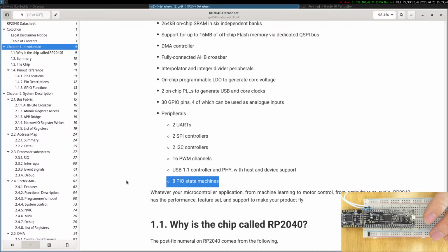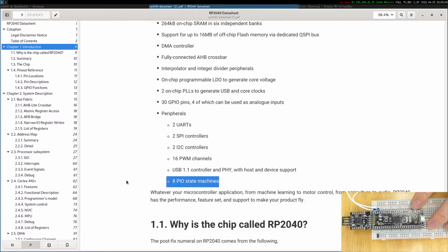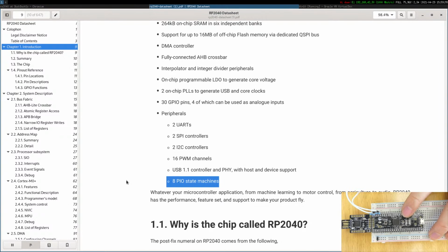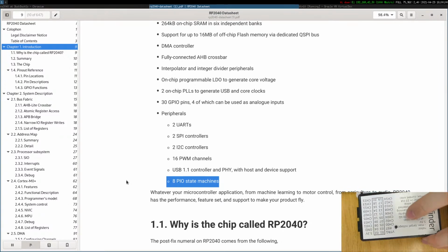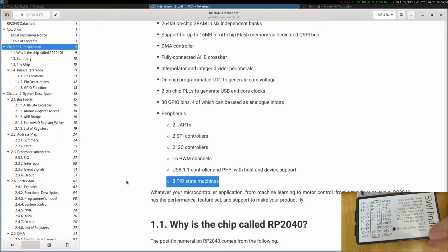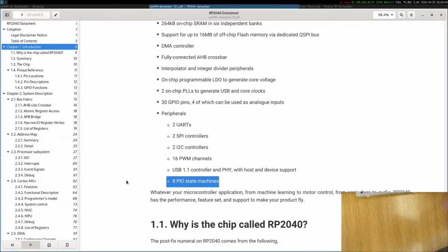They use their form data block, UDB. They use kind of resources. So the PSOC will probably not be able to have 3 UARTs, 4 SPI, and so on, and 2 I2C, which an STM32 would provide, and then tons of timers, which are baked in the chip. But I don't need all of them.